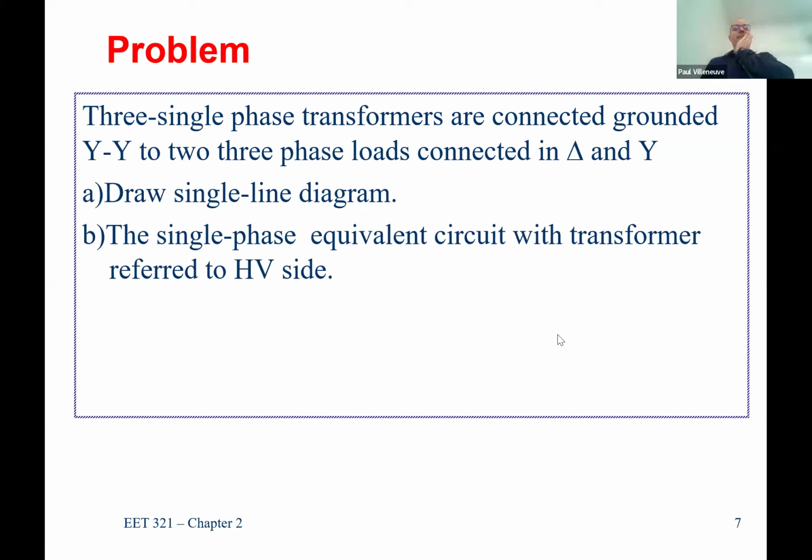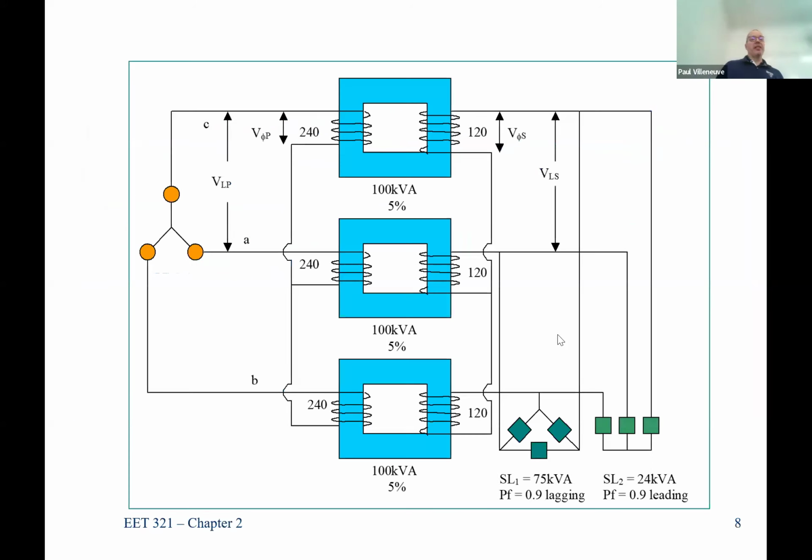So what we need to do is we connect those three single-phase transformers, and we're going to connect them in either delta Y configuration to go ahead and do that. Now, most of the time when you buy a transformer, it's a three-phase transformer all packaged up in one piece of equipment. They might even share a core, but the reality of it is internally, it's actually interconnected so that you have three individual windings around a core or a bunch of different cores, and then they provide the three-phase output.